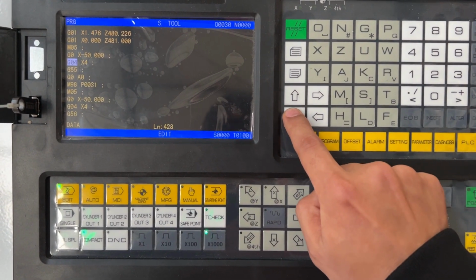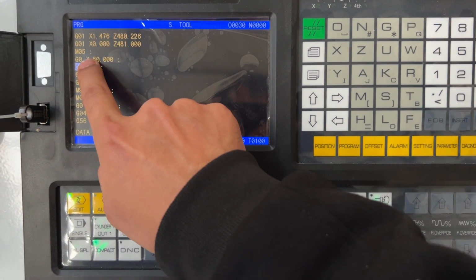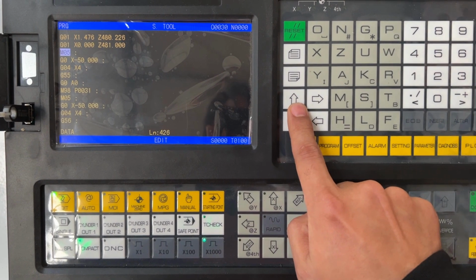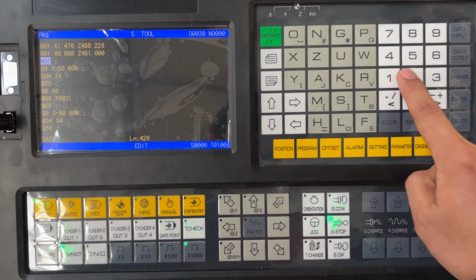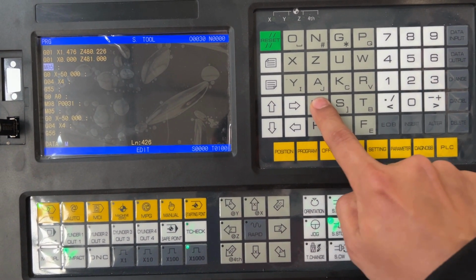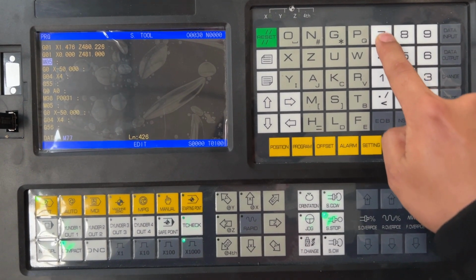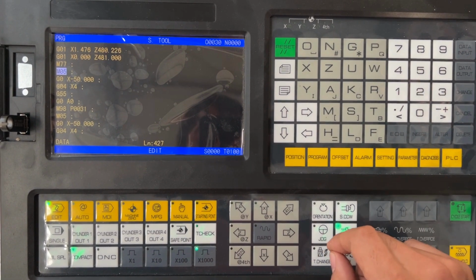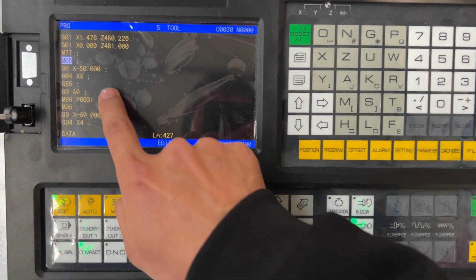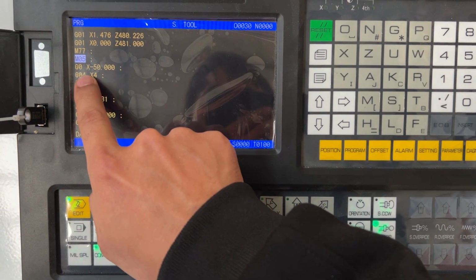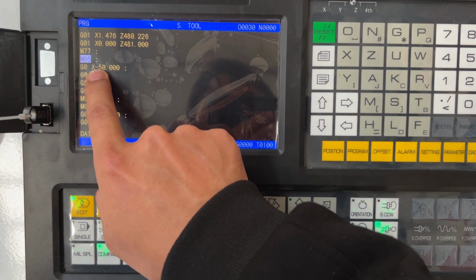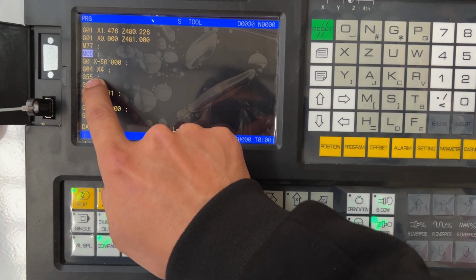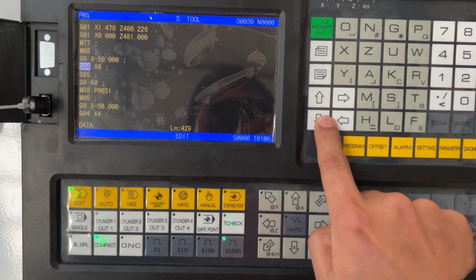G54. Add turning tool retraction code above M05. If your machine is a fixed turning tool, there is no need to add this code. M77 retracts the turning tool. After the turning tool has finished turning, it will automatically read the coordinates of G55 and run the file name of number 31.